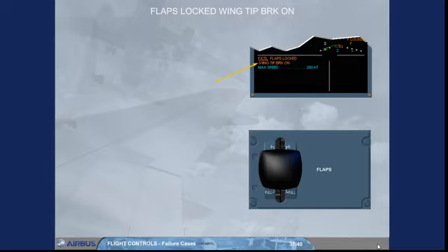The wing tip brakes, WTBs, are hydraulic devices which lock, when activated, the affected surface movement on both wings. For flaps and slats WTBs hydraulic sources information, refer to the FCOM.